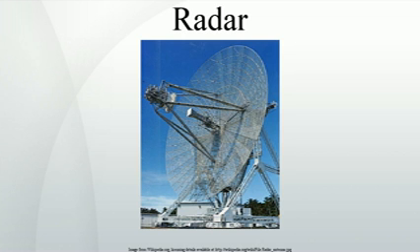Types of scan. Primary scan, a scanning technique where the main antenna aerial is moved to produce a scanning beam. Examples include circular scan, sector scan, etc. Secondary scan, a scanning technique where the antenna feed is moved to produce a scanning beam. Examples include conical scan, unidirectional sector scan, lobe switching, etc. Palmer scan, a scanning technique that produces a scanning beam by moving the main antenna and its feed. A Palmer scan is a combination of a primary scan and a secondary scan.